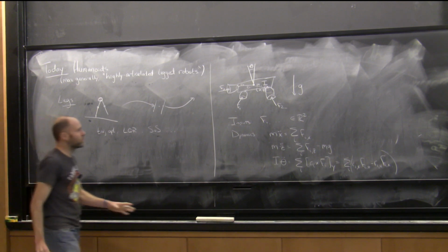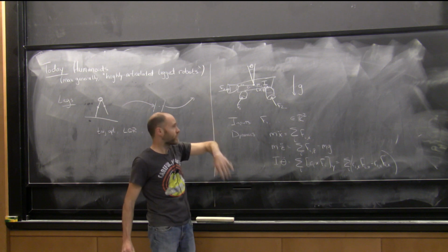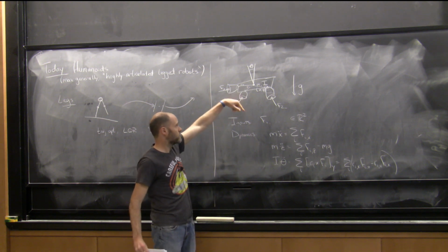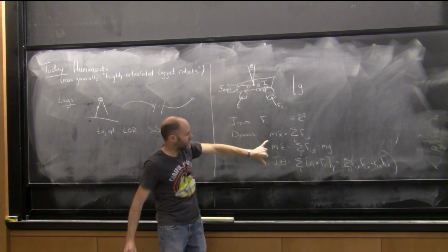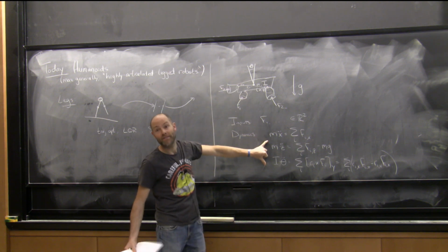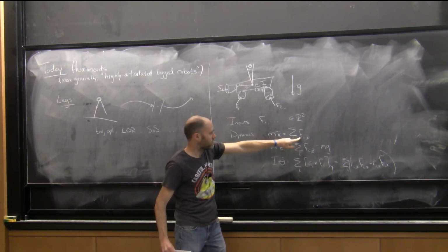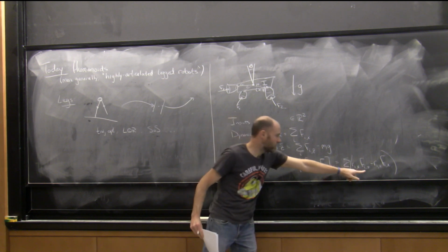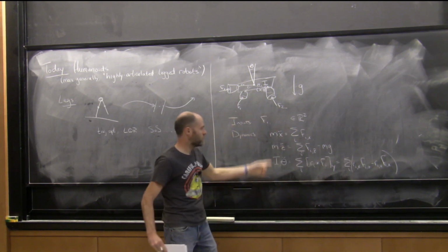So this system, even though the planar quadrotor was a nonlinear thing, we had to linearize it or whatever. If I'm willing to tilt my rotors or have my thrust vectored, then actually the dynamics are linear. Well, they're affine. I have a gravity term here, but the forces all appear linearly if the locations here, of course, are constant.